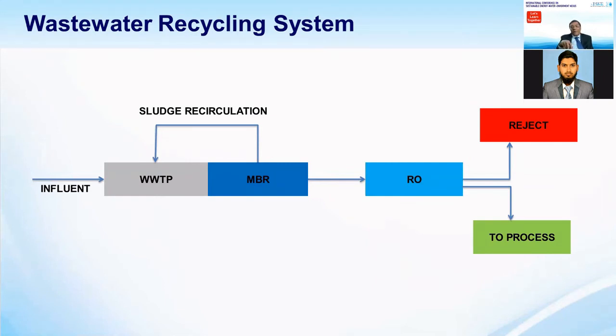One is submerged, the other is outside, dry. The pros and cons of the submerged membranes and the ones placed outside are different. People prefer to avoid submerged membranes, as maintenance of the system is easier when it is outside.